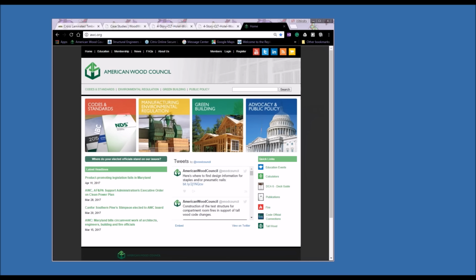Now, if you're going to 12 stories or 18 stories like the Framework or Brock Commons, you're really not going to want to use a gravity system where you have columns landing on floor plates, resting on columns. You're really going to want to provide a stiff element through the floor zone instead of having the floor plate itself taking that load, not just for shrinkage, but for load carrying capacity reasons as well.